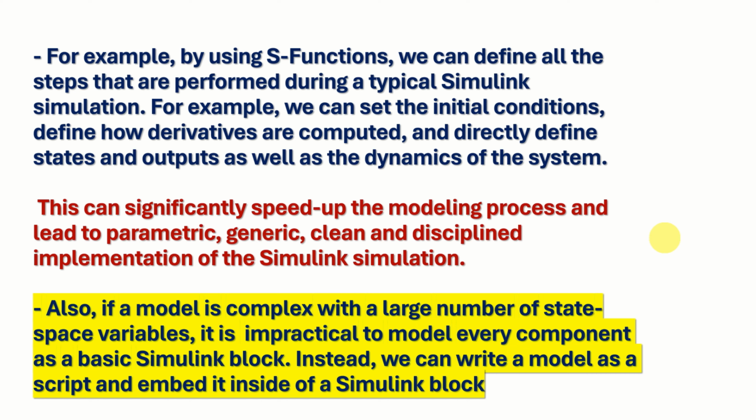simulation. Also, if a model is complex with a large number of state space variables, it is often impractical to model every component as a basic Simulink block. Instead, we can write a model as a script and embed the model inside of a Simulink block. For that purpose, we use S-functions.